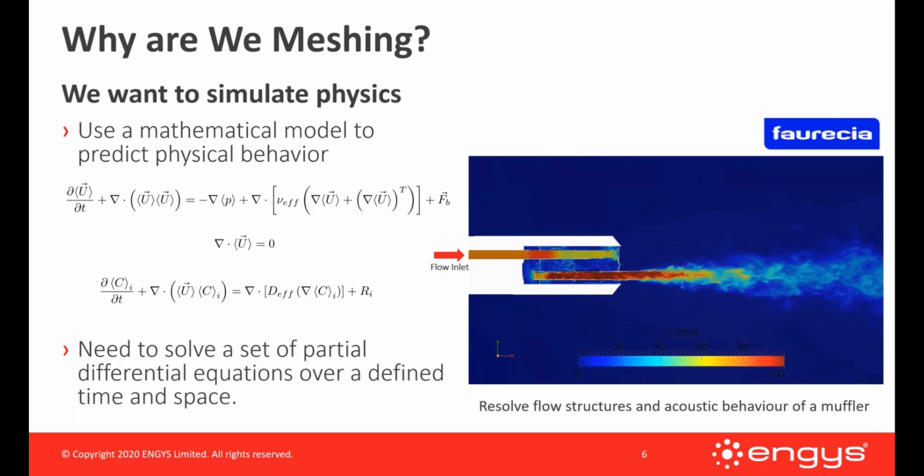If we're talking about pressure waves moving through a domain and resolving these flow features that may cause these acoustic waves, then we need to have a very large degree of control over how we mesh, how we refine, where we add layers within the domain. So this was a particularly interesting case.